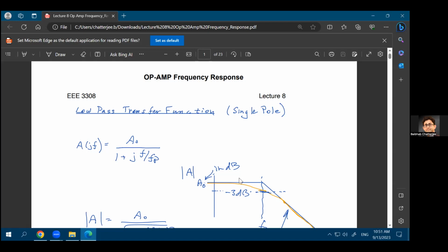What happens in that case? You already have this transfer function, 1 over 1 plus S times R naught times C naught. Now, let me write that over here. When your omega is equal to 1 upon R naught C naught, your transfer function becomes 1 plus j omega times R naught C naught, and then you replace your omega with 1 upon R naught C naught.